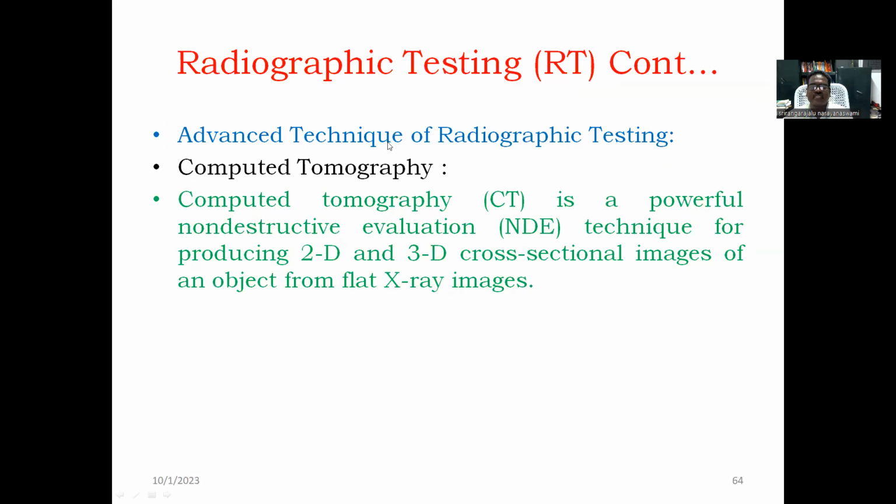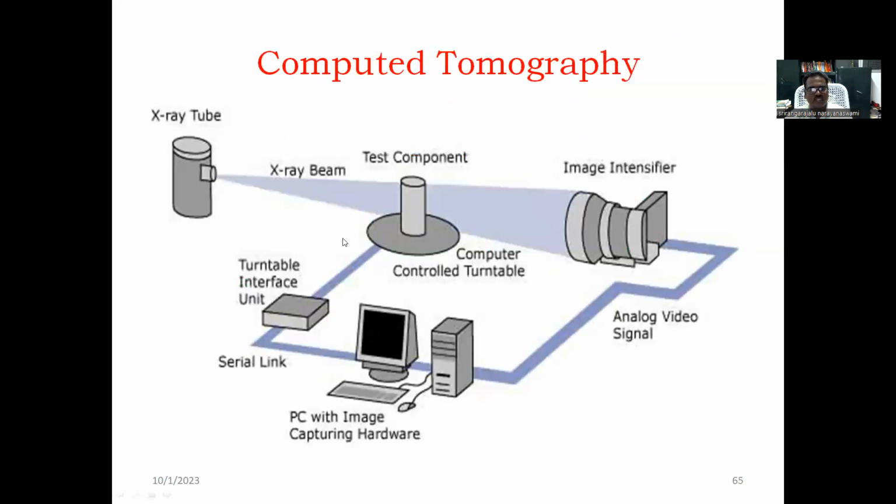And an advanced technique of radiographic testing: computed tomography. Computed tomography, CT, is a powerful non-destructive evaluation, that is an NDE technique, for producing 2D and 3D cross-sectional images of an object from flat X-ray images. So this is the computed tomography. This is an X-ray tube, X-ray beam, test component, image intensifier, analog video signal, computer-controlled turntable, and here they will have a serial linkage, turntable interface unit, and a PC with image capturing hardware. This is the computed tomography setup.